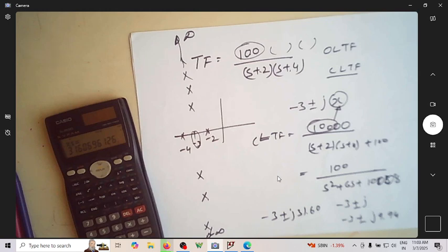The main thing is, an open loop zero will have to settle down in a zero. Where is the zero? A zero can be a finite value of the transfer function. If there are no finite values, then it has to go and terminate at infinity. If it is a finite value, then you can see this is sitting here, this is sitting here, this is sitting here. As the value of this k increases, the closed loop pole position is moving towards infinity.